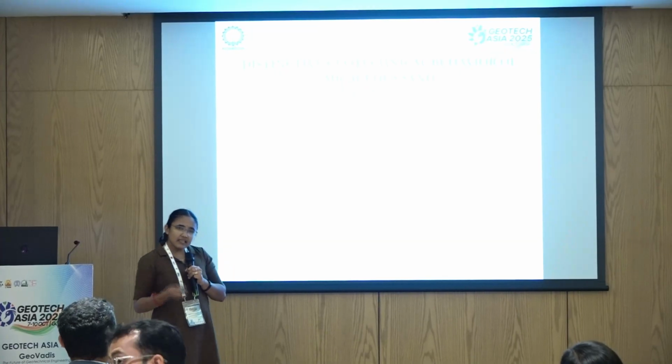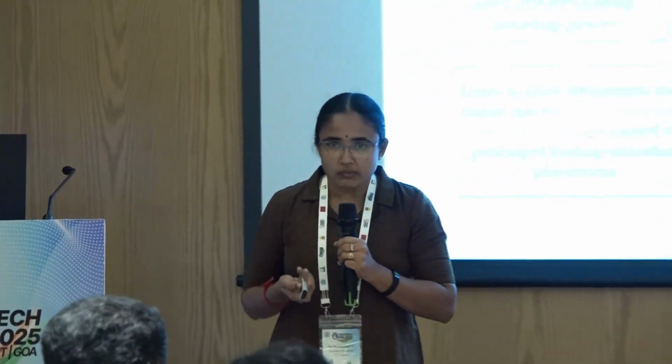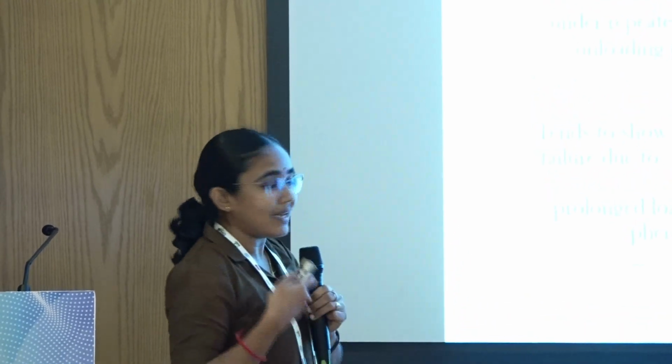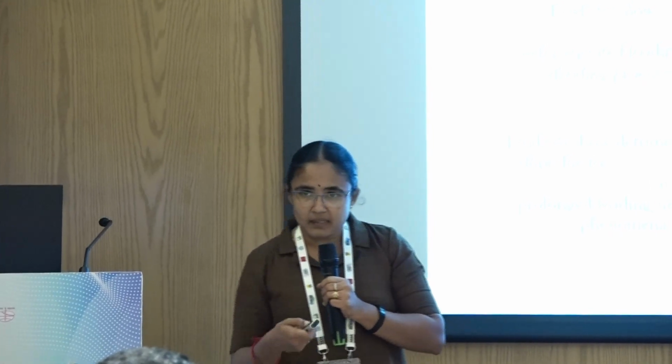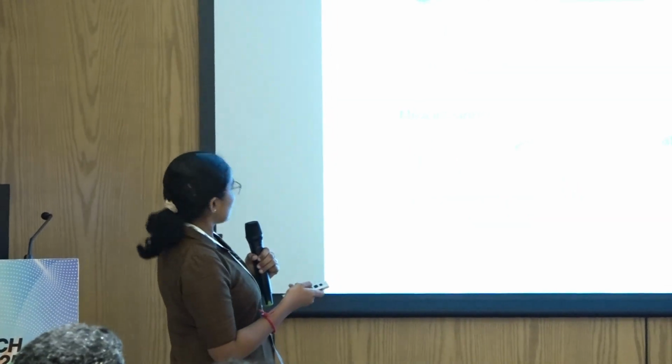That's why in literature, micaceous sand which has more than 10% mica is usually considered not suitable for pavements, and it is usually taken away and replaced with new good quality material. But this study aims to understand the basic microscopic mechanism which happens during crushing, and if any parameter gets deteriorated during crushing, how it can be regained using alternative sustainable stabilizers, not cement or lime.